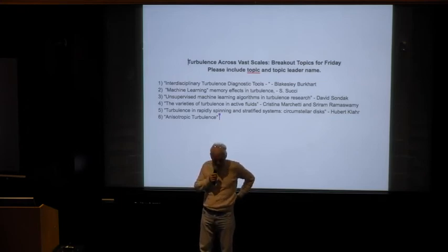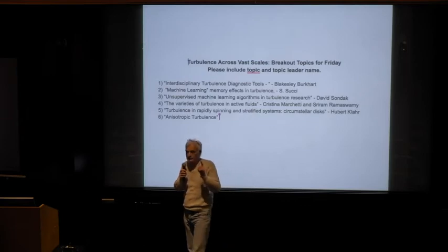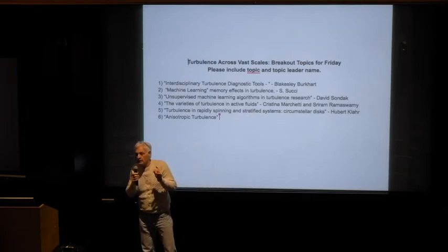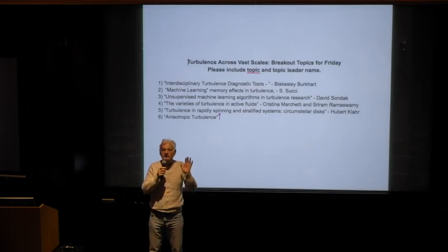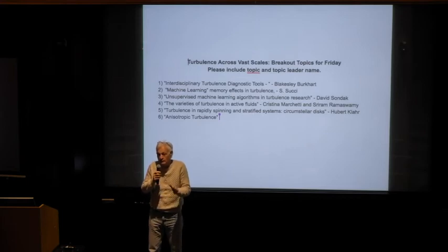And what else? The point which I would still like to make is that maybe it's not obvious to everybody that there is nothing like viscosity in the kinetic world. Viscosity is an emergent property, whereas relaxation is a fundamental mechanism. And the two only coincide when turbulence is in equilibrium.